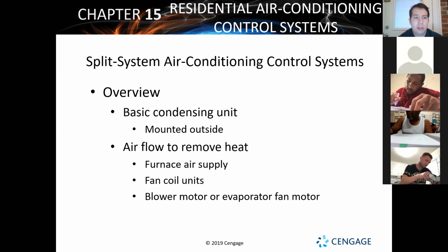It's one of the things for any kind of heating and air conditioning system. If you've got some problem and you're trying to figure out, I don't know what it is. I've checked all my voltages. I've checked all my components. I really think it's working fine. I think it's coming on, but it's just not cooling or heating as much as it should. Start looking at airflow. Airflow is one of the most common things that'll stop a system from cooling or stop a system from heating.